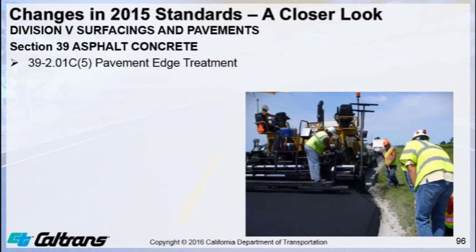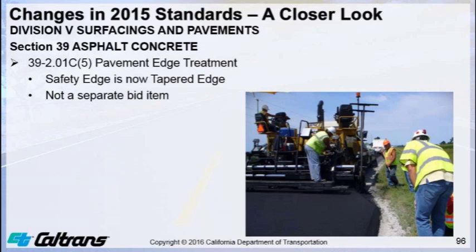Continuing on in Division 5, surfacing and pavements, we'll talk a little more about asphalt concrete. So in Section 39-2.01C5, there's been a terminology change from what we used to say: the safety edge is now being called the tapered edge. And this change has been made both in the specifications and on the standard plans. The tapered edge is not a separate bid item, so the cost of installation is included in the payment for the bid item for hot mix asphalt or for concrete pavement.